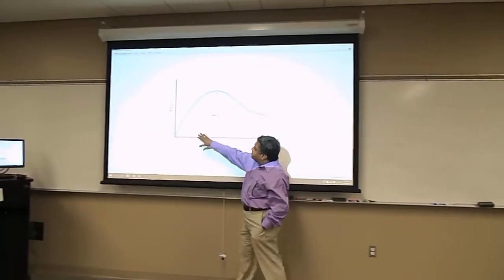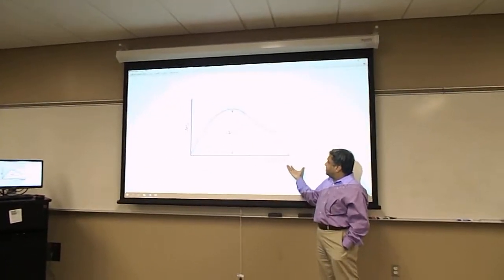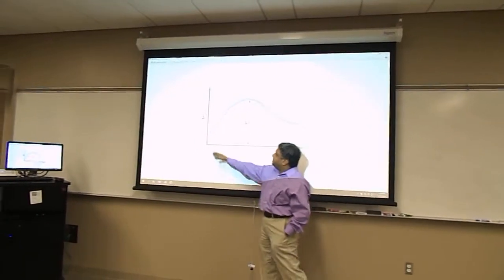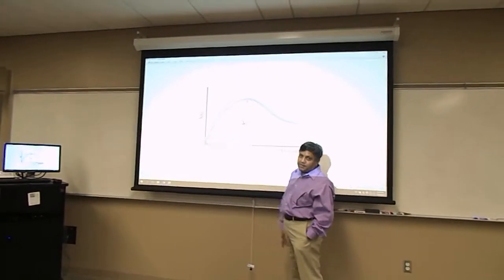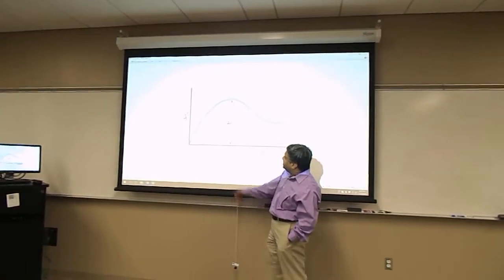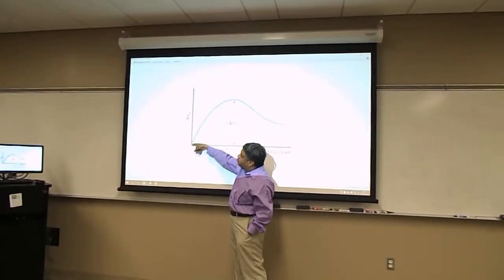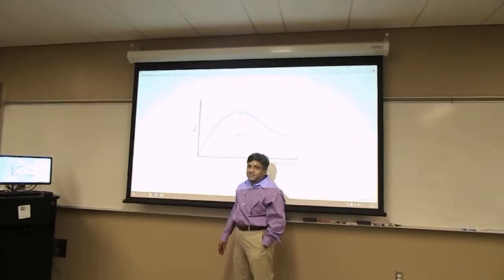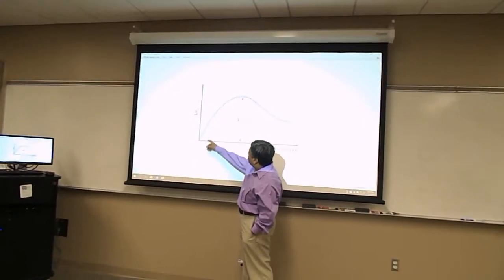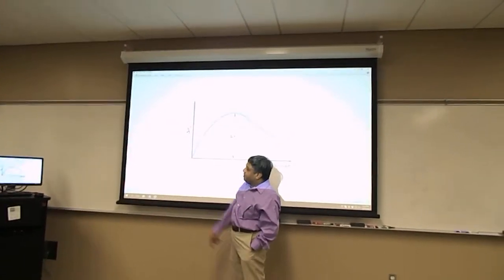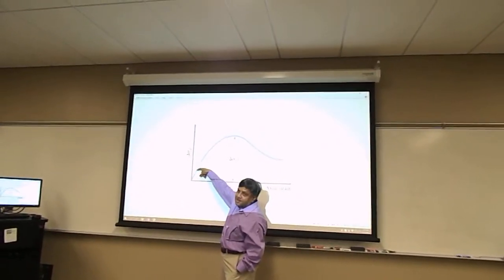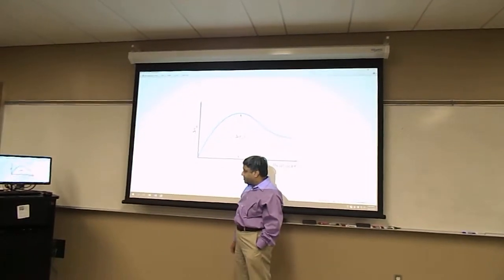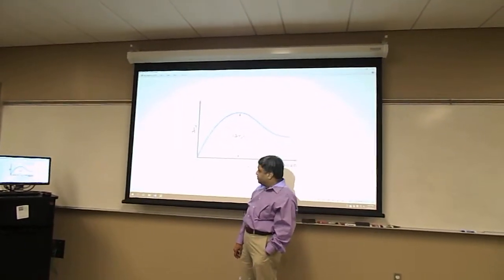The modulus of elasticity can be obtained from an axial strain versus deviator stress curve, pretty much the same way as you did in your strength of materials. If we have a straight line portion here, up to the proportional limit, we can take the slope of that line as the modulus of elasticity. But most of the times in soil testing, we get this curve right from the beginning, so there is not really any straight line portion. So that's one reason we want to use another method.